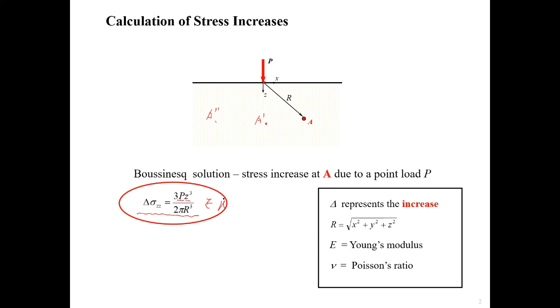Which means it doesn't matter what type of soil I have. Whether it's clay, sand, gravel, silt, or organics, we come up with the same stress increase. In other words, the soil type does not matter when we talk about the Boussinesq method. So one of the advantages is that I really don't need to know anything about actual soil conditions to estimate what the induced stress would be from the load I'm applying to the ground surface.